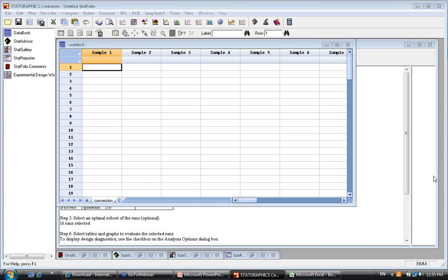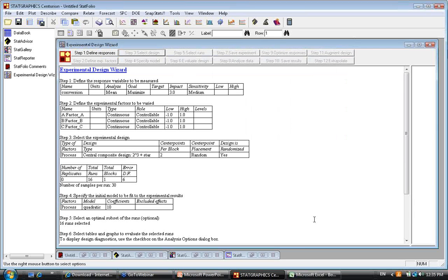Question, last question. I think it's the last one, yeah. Can you use mean even if you have an orthogonal design? Yes. Even if you go in and set up a Taguchi type design in orthogonal array, you can choose to model the mean as well as one of Taguchi's signal-to-noise ratios. Taguchi prefers certain signal-to-noise ratios, but we still give you the option of building a model for the mean or for the standard deviation or for the coefficient of variation in addition to the Taguchi signal-to-noise ratios.